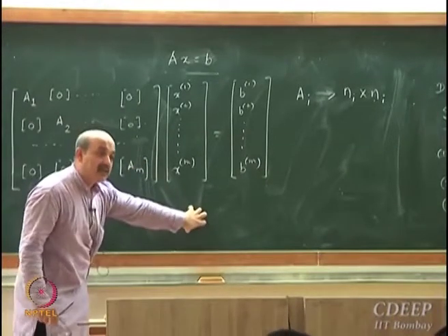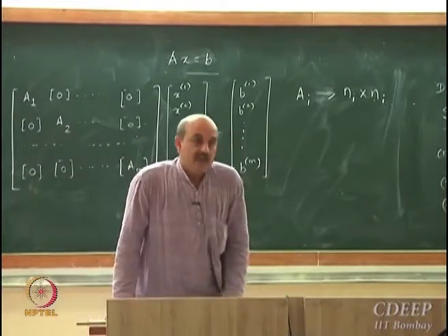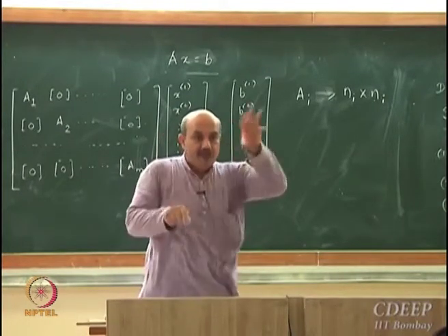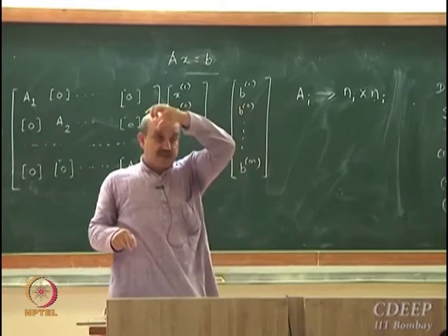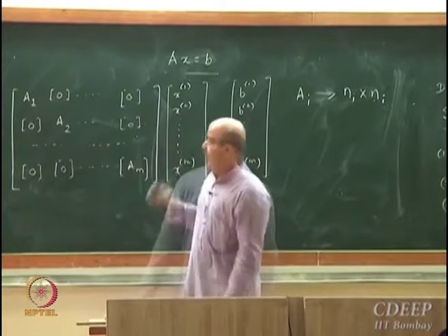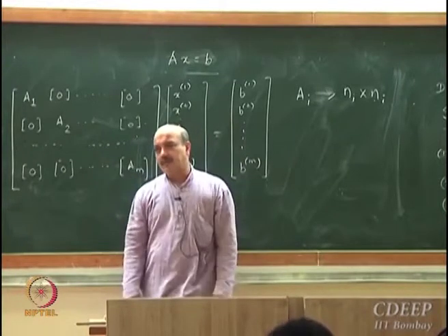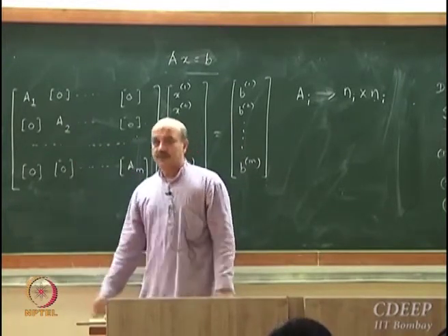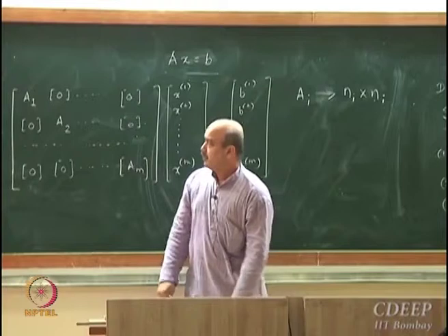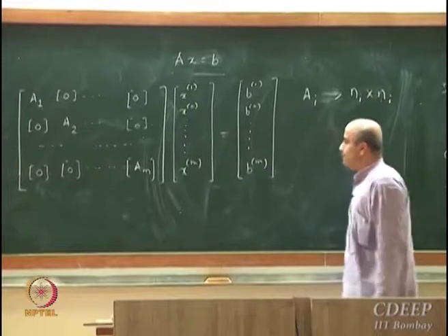Only these matrices on the diagonal are dense, because if you remember, when you do orthogonal collocations on finite elements, only variables in that small segment appear in that equation. Okay, so you have this funny structure that you will get. Well, will you get this, or will you get some overlap? Probably in OCFE you may not get exactly this structure, you might get some overlapping and you will have to do some more tricks to bring it to this form.